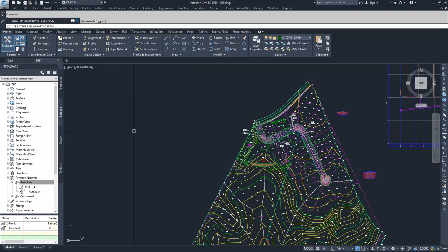Civil 3D would stop for a little while depending on the strength of your computer, because there is an absurdly large amount of information inside of the pipe networks catalog. Also, depending on which catalog you have selected, some of them have a lot more than others, but it takes a little while for it to complete an entire parts list using the create pressure parts list full, and it takes a long time to wade through all the information.